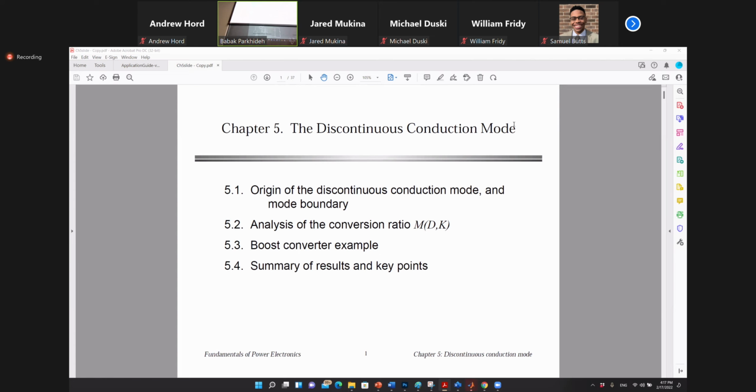So going back to our question. Imagine that I operate this synchronously. When I turn this on, I turn it off, and vice versa. In other words, I do not have the diode. So you would say that you do not have the reverse recovery of the body diode. Is that true, or am I missing something? I think you're missing that little diode going into the drain of the MOSFET.